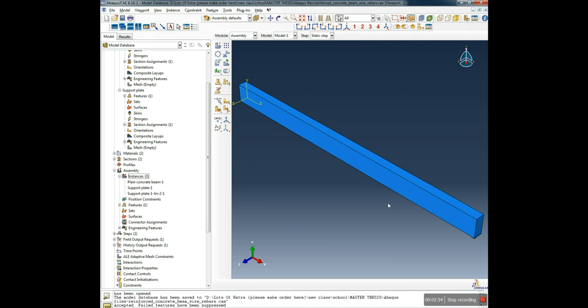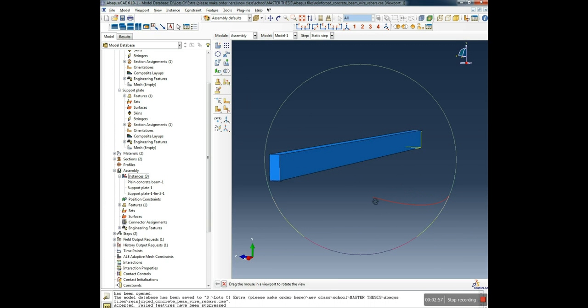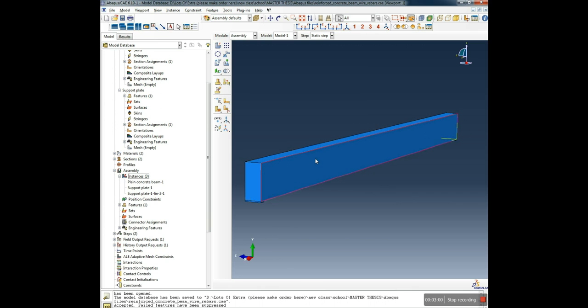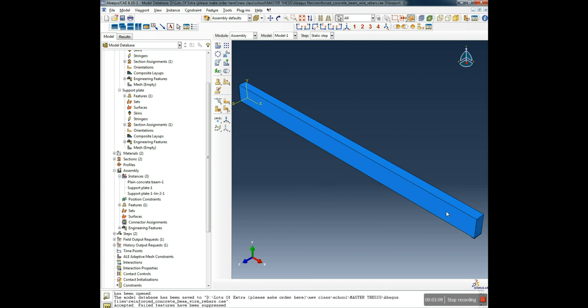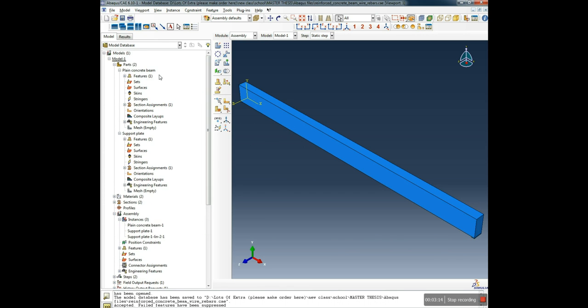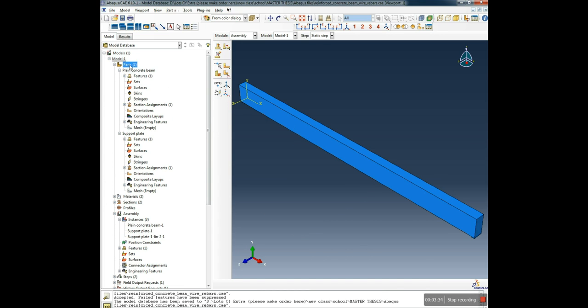So now we have the supports, and I've done that. I used the old solid rebar model to go for the wire model, so we don't need to place the supports in the exact position, and we have the material defined for concrete and steel in the same way as before. And right now we are gonna save it. We have here wire, so we don't have the solid, so we don't mess up everything that we have done before. We go to the floppy button and we click, so we save. Database has been saved.